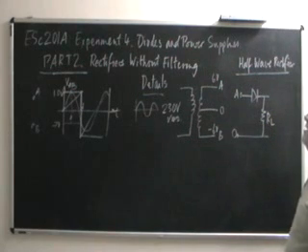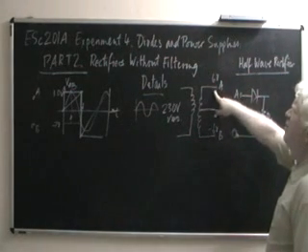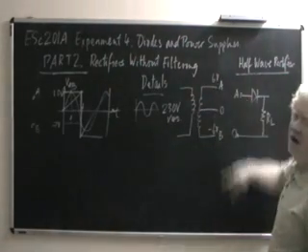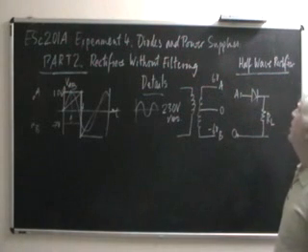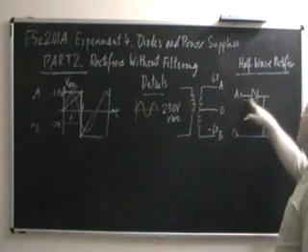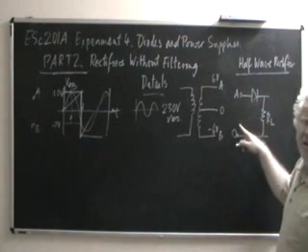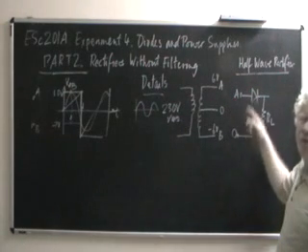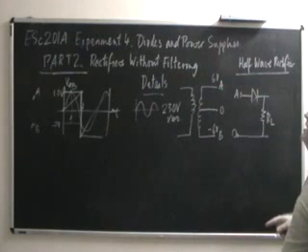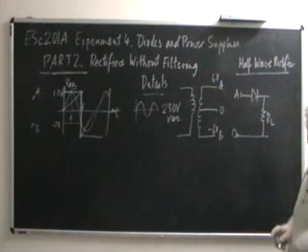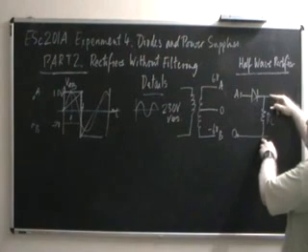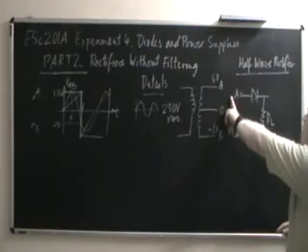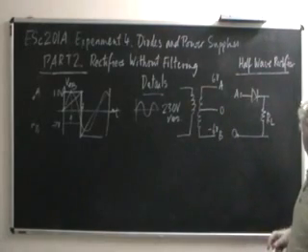Now what happens? When A has a positive, these are both alternating voltages. The values given here are the RMS values, root mean squared values. What we do here is observe what happens in different parts of the cycle. When A goes positive with respect to O by any positive amount, this diode conducts. We can use here the ideal diode model, and so what will happen here across RL is that the voltage between OA is transferred to RL.